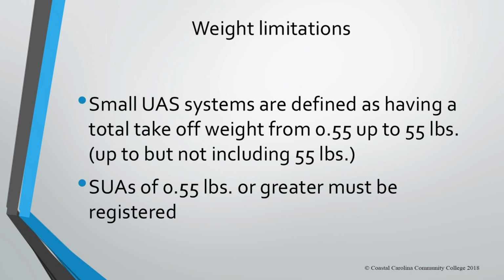Weight limitations. Small drone systems are defined as having a total takeoff weight from 0.55 pounds up to 55 pounds. Drones of 0.55 pounds or greater must be registered. 0.55 pounds is equivalent to 250 grams. So sub 250 gram drones are subject to special regulations.